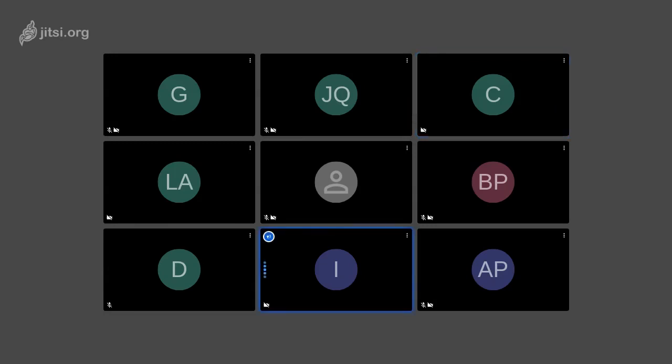Yeah, the thing is that first of all, maybe you don't have all the information. So I can have a wall, and maybe there is also a material assigned, and this could be okay. And then you have a beam that is connected to this wall that has a material, and maybe even a section, although it has the geometry already drawn. But the thing is then that you need the engineer to put more information. So what are the material properties, and what is the connection of the beam to the wall, because there can be different kinds of connections.